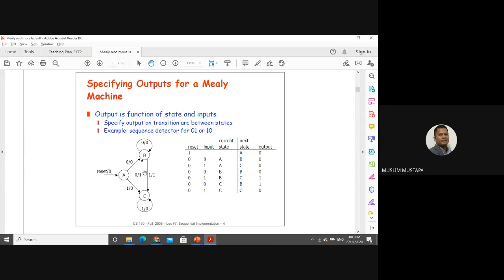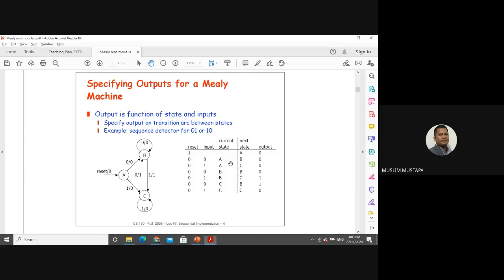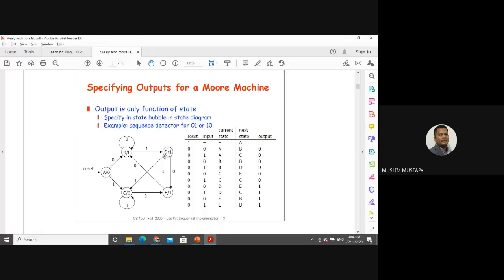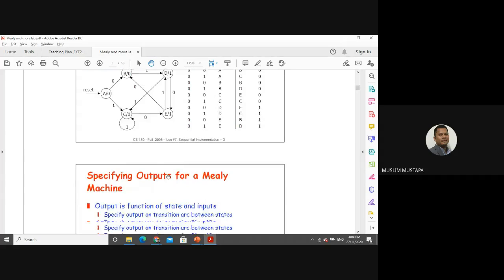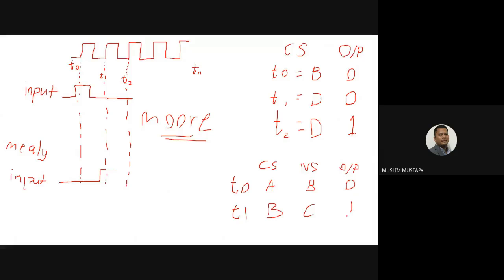So it's going to the next state. Next state is C, current state is B. As it goes into the next state, we see the output value here, which is 1. The output value we refer to is the number after the slash for Mealy. But for Moore, the output refers to the number inside the circle. That's how we get the output equal to 1.